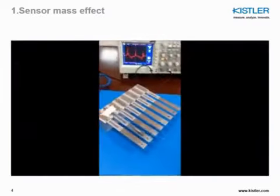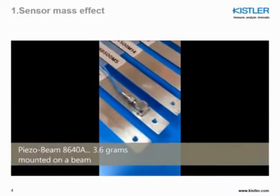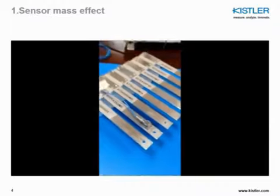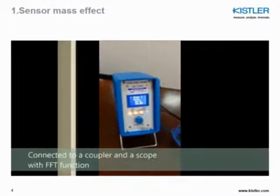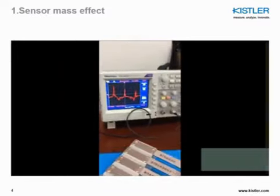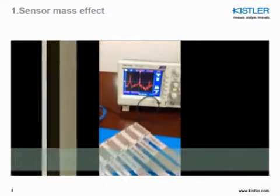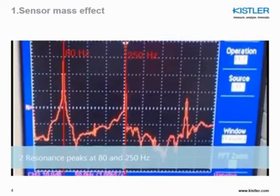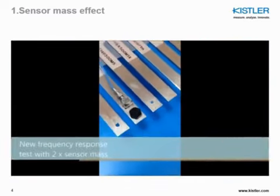We are here performing a very simple test using a very simple demo setup made of a cantilever beam. We are mounting one of our piezo beam 8640A sensors, which is 3.6 grams, which is not really negligible compared to the mass of the beam. We are going to perform the shock test to excite resonance and look at the first two resonance peaks that are showing up at 80 Hz and 250 Hz.